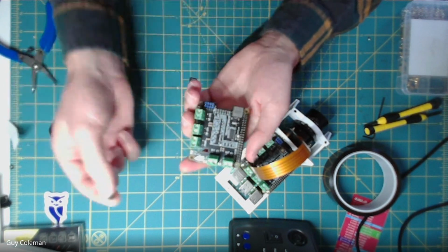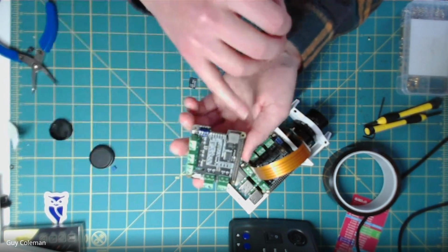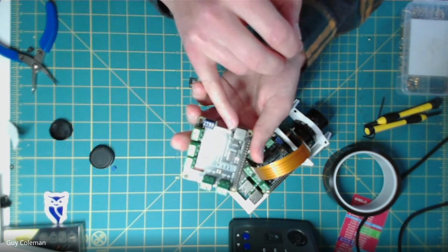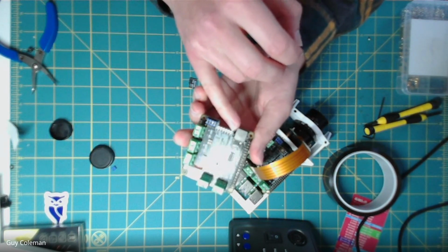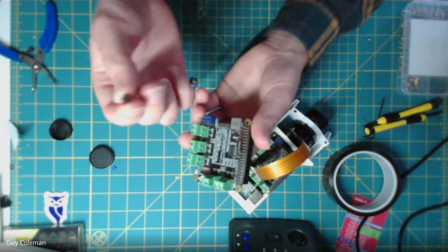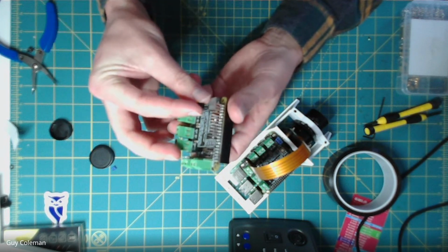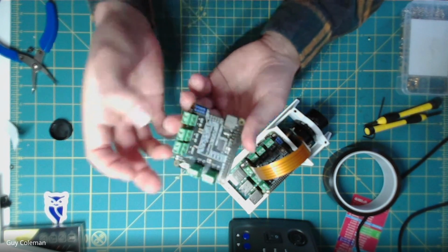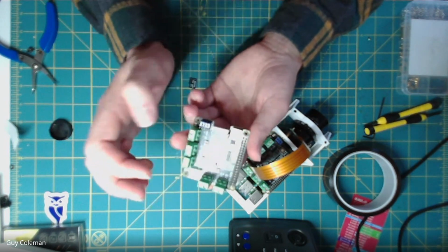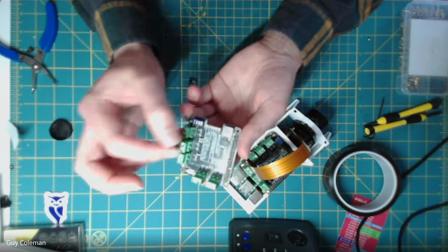This is probably the most important one, and I've made the mistake of telling my brother it wasn't working, but it was working. I just forgot to put this enable power pin on. This just connects the Pi to the power supply just next to it. So you definitely need that one to make sure everything is running correctly. Make sure it's the right way around. Alternatively, if you want to power the Pi separately, say through the USB-C, you'll need to remove this for sure.